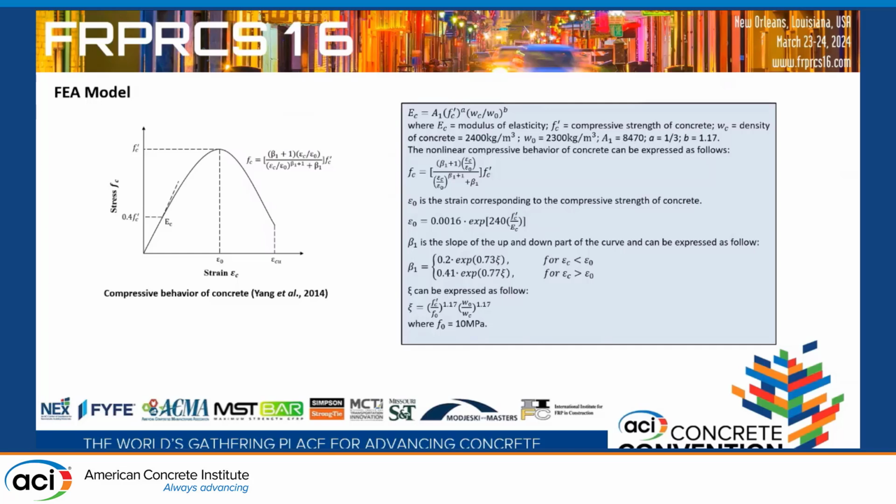So when we do the simulation, the most important thing is the property of the materials, right? So the first is the compressive behavior of concrete. I used the compressive behavior of concrete recommended by Young. It's Young's model, a very popular model when we use ABAQUS to simulate.